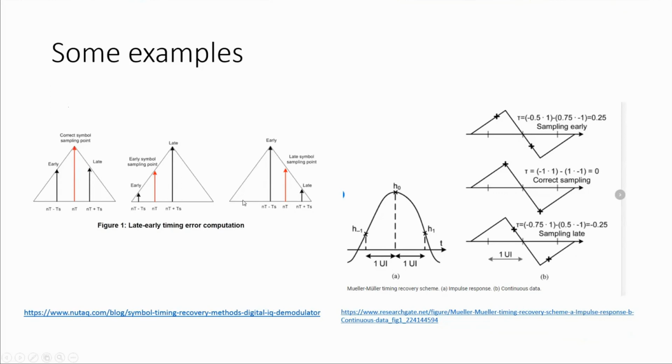So one thing that's important to understand about this is if your clock rate is, say, 1 sample per second, you actually need 3 samples per second to figure out what the right time period is. That's not something that is easy to get from literature. If you just crack open a book on this, it's sometimes confusing to realize you have to have multiple samples at a higher rate than your data clock to make this work.